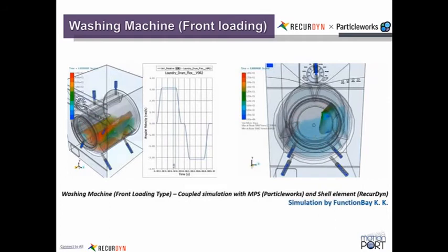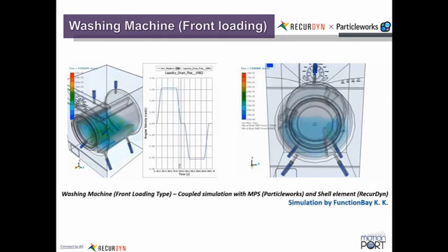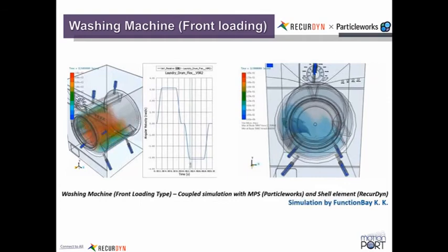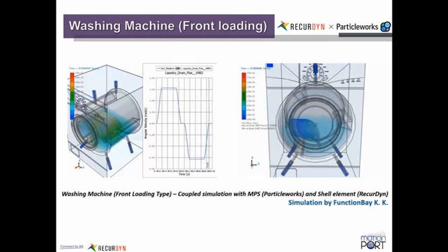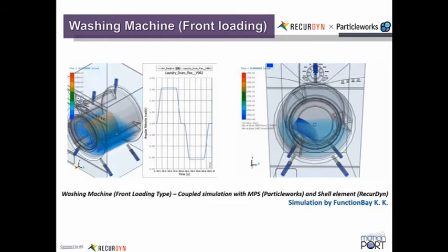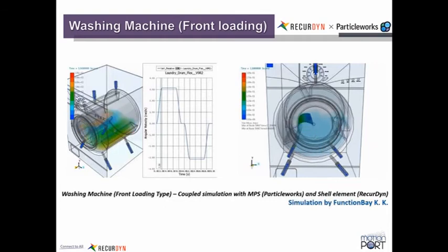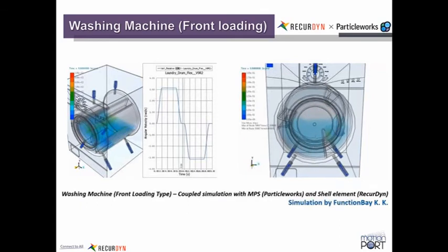Yes, it certainly is. If you were to monitor the attachment points between the fuel tank and the chassis, there are several of them. If you were to have the tank half full of fuel versus 1/4 full of fuel, and then looked at the reaction loads, you'd see the difference. So yeah, it's all coupled.